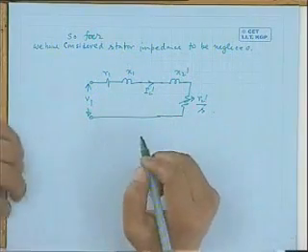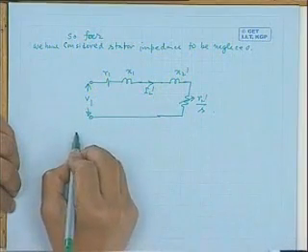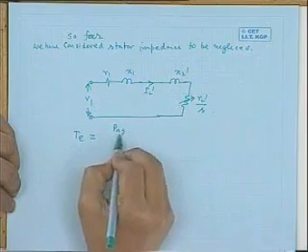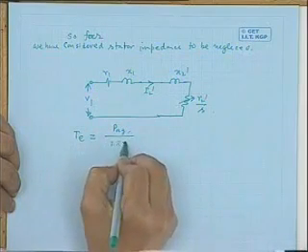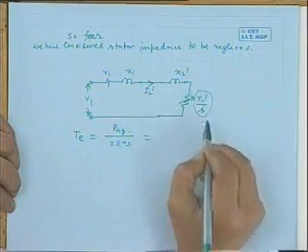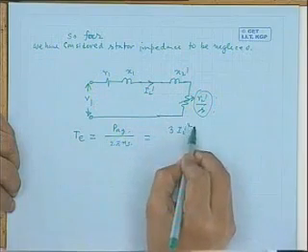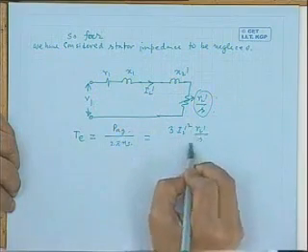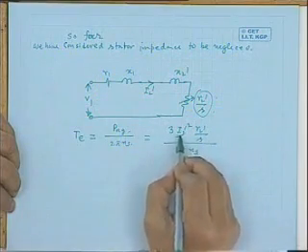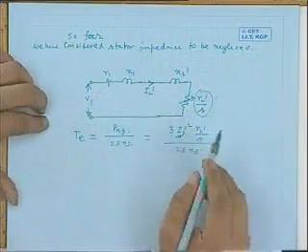And I want to find out a more correct expression of the torque. This will be your I2 dashed. I will tell you the guidelines, you will complete it. Tell me, what is the electromagnetic torque, in the same line? It is air gap power by 2 pi ns. What is air gap power? Power in this resistance. So this is I2 dashed, so 3 I2 dashed squared R2 dashed by S, same thing, 2 pi ns.